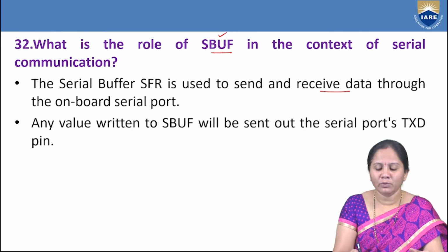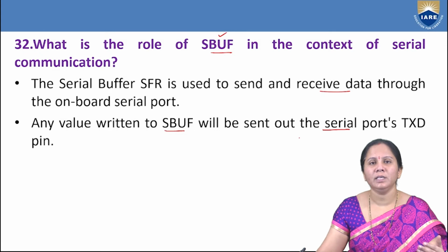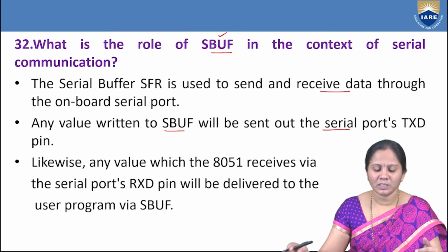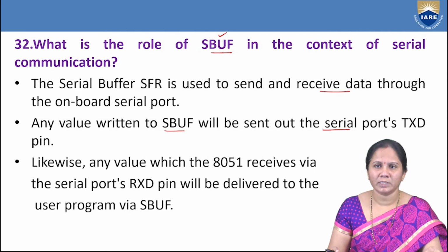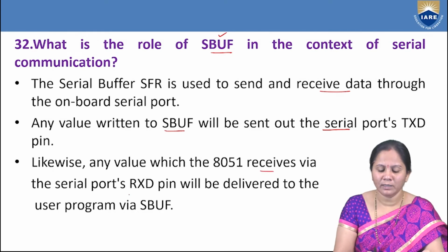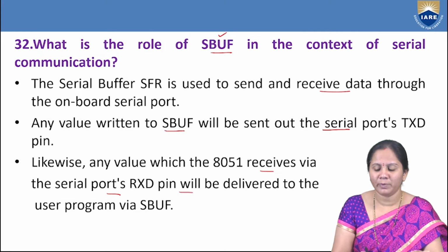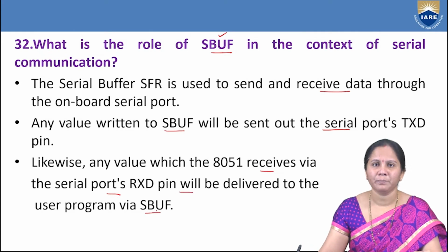Any value written into this serial buffer will be sent out of the serial port TXD pin. Similarly, at the receiver end, RXD, we also have an SBUF register. The 8051 receives the data present at the serial port through the RXD pin, and it is kept in this SBUF register.